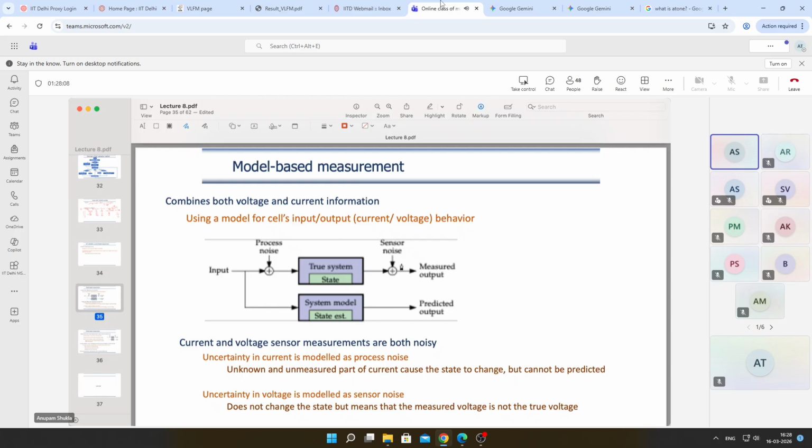Now it is implicit in our discussion that the method self-corrects. So what happens is if it finds that the voltage it has estimated is deviating from the measured voltage in ways which are not expected out of normal distribution differences, then the model will use that difference between the predicted and the measured voltage to update the parameters of the model. Okay. So it will update the R0 value or the C1 value or the state of charge in order that the predicted value and the measured values are within the random noise distribution. So therefore, that brings in the self-correction power of these methods.